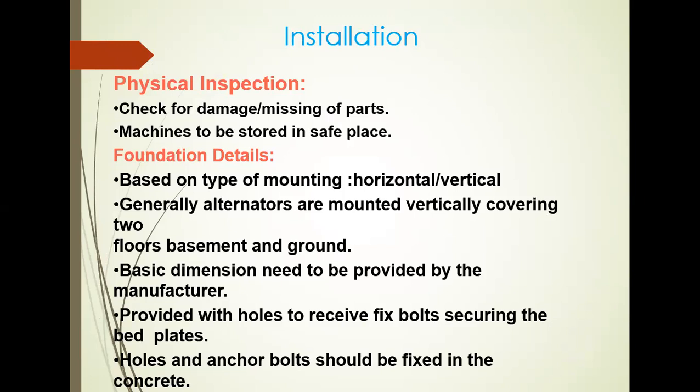Then after that, the main important topic is installation, foundation and installation of synchronous machine. So first physical inspection is needed. So first this area selection is needed. There we have to check the damage and missing of the parts, and the machine is to be stored in a safe place. That physical inspection is mainly needed.